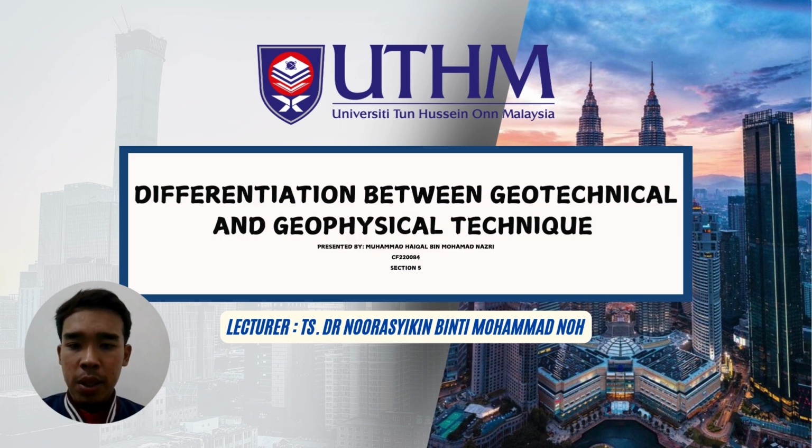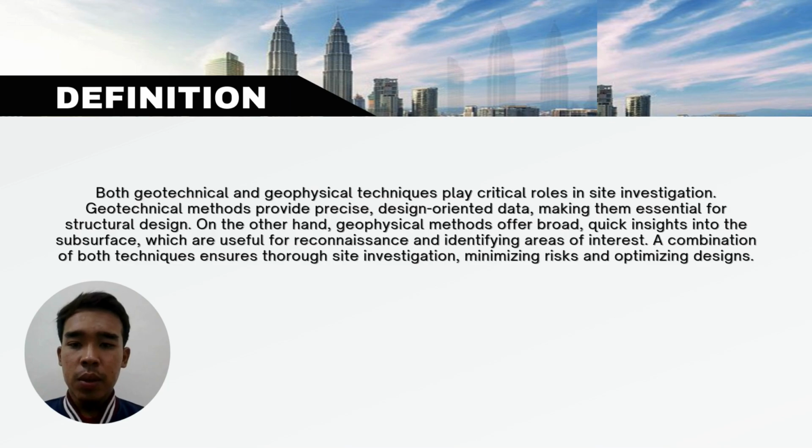Today I will be explaining the differentiation between geotechnical and geophysical techniques. For the definition of geotechnical and geophysical, both techniques play critical roles in site investigation. Geotechnical methods provide precise, design-oriented data, making them essential for structural design. On the other hand, geophysical methods offer broad, quick insight into the subsurface, which is useful for reconnaissance and identifying areas of interest. A combination of both techniques ensures a true site investigation, minimizing risk and optimizing design.